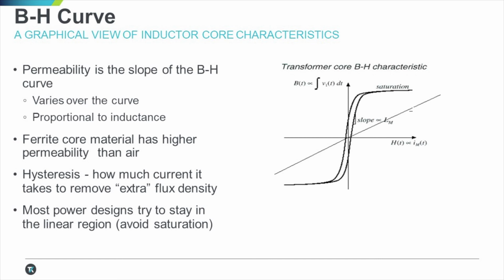Let's talk about the definition of a BH curve. It is effectively something that will visualize the performance of an inductor and its cores. Now, designers use the BH curve, or hysteresis curve, like the one shown in the above figure. Within the equation, H is the magnetizing force in the device. It is measured in amperes per meter and is proportionate to the current. Now the resultant flux density, B, is proportionate to the integral of voltage.